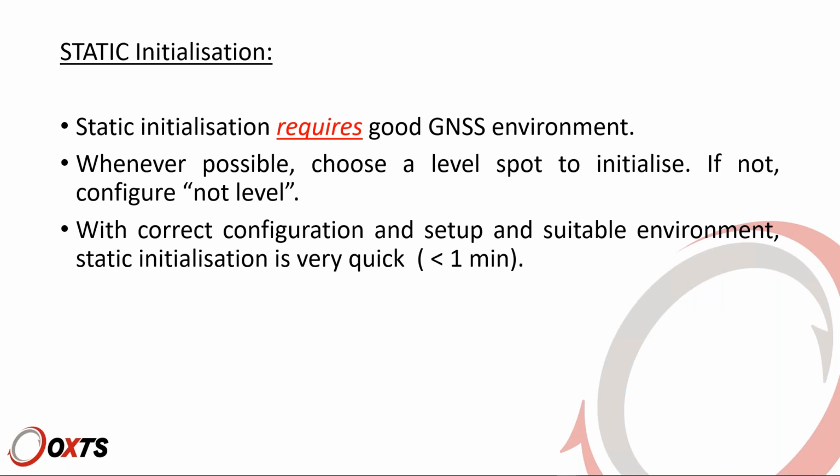Another option is static initialization, whereby the system initializes thanks to the data from the 2 GNSS antennas. But if you do that, remember that because you are not moving, the IMU is silent, it's not providing meaningful data. The system is completely relying on GNSS data, so the GNSS data has to be good if you are initializing statically. So you need to be in an open sky environment, not in between buildings. If you have a correct configuration, then static initialization can be very quick, under a minute.